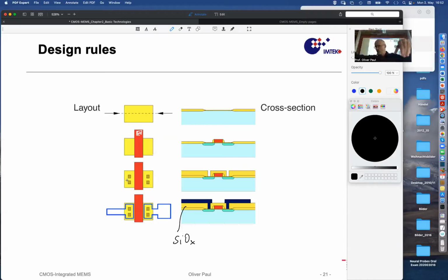And if you have one type of structure, small hole, slit, big holes, you can be sure that at the big holes, the etching is going to maybe be faster than in the small hole. And so once you're finished with the big hole etching, you need to continue etching, and thereby you continue etching whatever there is, and you over etch, and that may not be good. So to guarantee homogeneity, you limit your designs to as few variants as possible, and this is done in this particular way with these via holes.